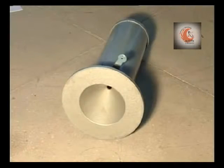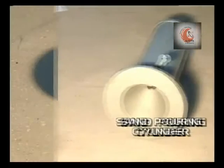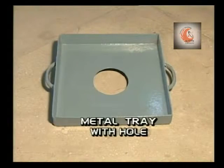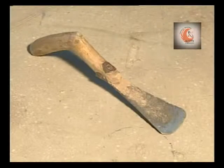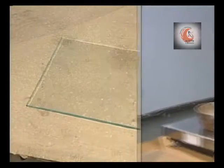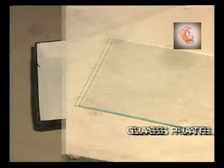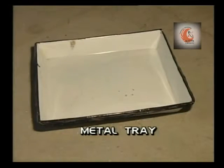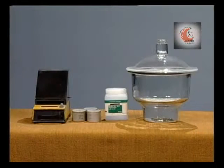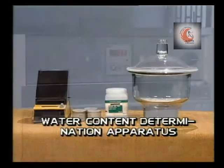The apparatus required for conduct of this practical includes sand pouring cylinder, cylindrical calibrating container, metal tray with hole, excavating tool, balance, glass plate, metal tray, sufficient clean uniform sand passing 1 mm and retained on 600 micron IS sieve, and water content determination apparatus.